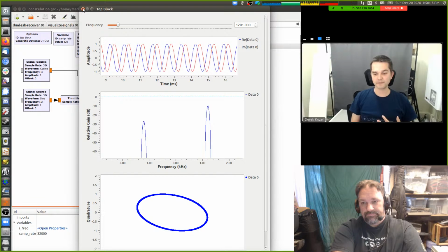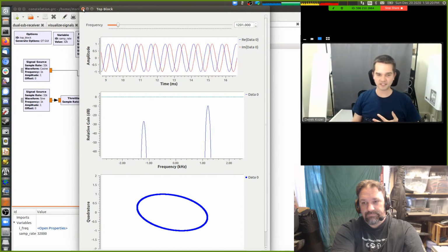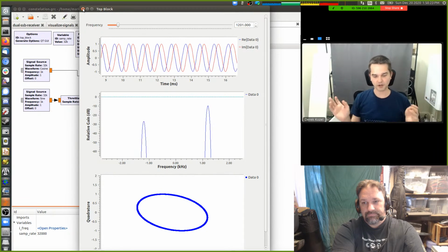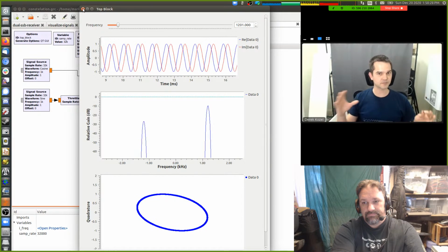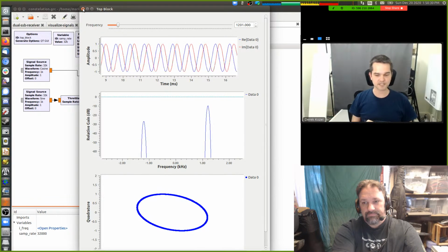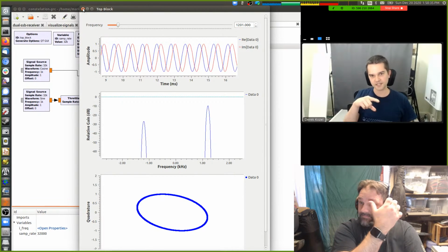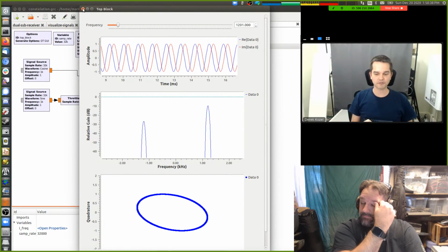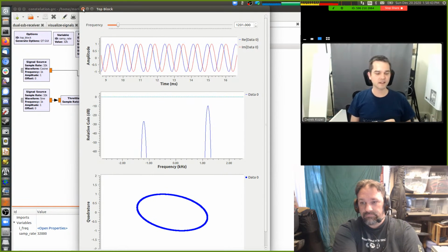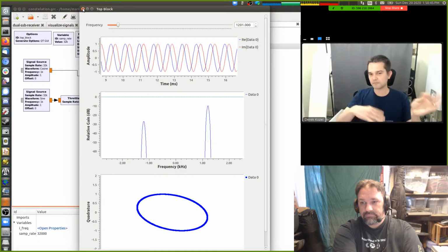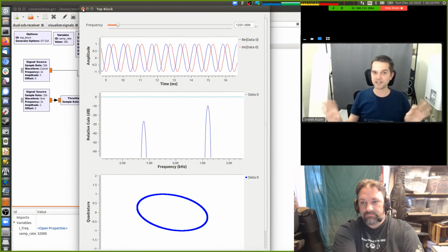And because you're outputting data fast enough, you can create a single sideband signal at 7 megahertz, and it's fine, because Shannon's theory and the sampling theorem say that as long as you're outputting more than 14 megasamples per second, twice the highest frequency of your signal's component, then it's unambiguous. It's fine. You can put an arbitrarily complicated signal in, and you get it out. And so single sideband doesn't have any issues here.